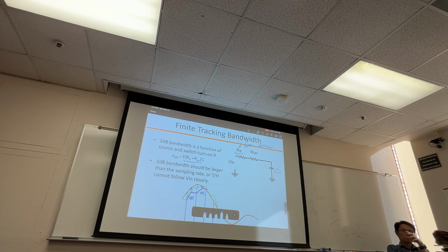If I want low output resistance, I need to add an output stage. Usually it's an output stage, right? So you make the resistance low. Those are the different trade-offs to consider. So you do need to add that additional output stage to have a smaller RS. Usually you will take more power. That makes sense? You want to reduce that resistance. Or you can put it in the feedback loop, right?